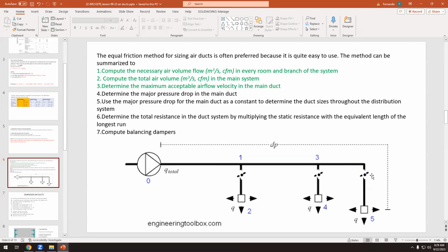Okay, and it takes time because you have to check all the systems, you have to check all the airflow, and you have to measure the airflow with equipment to do that. But yeah, probably because it takes time and people don't know anything about it, we all take for granted that when we are having a warm shower, if someone opens another bathroom, we will have cold water. We take it for granted. It's like unavoidable, like the law of gravity. Well, it's not. It's just checking the circuit and working with these valves and making sure that each tap or each diffuser has the right water flow or airflow.